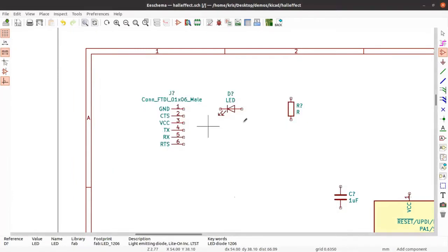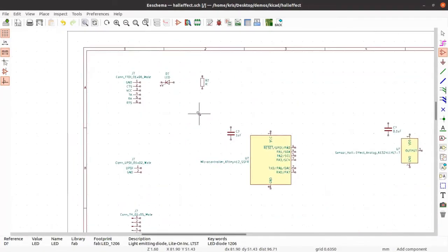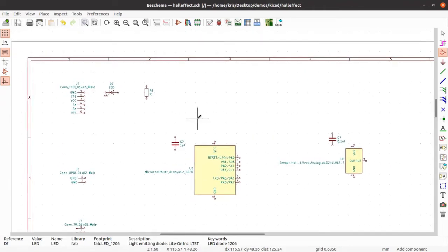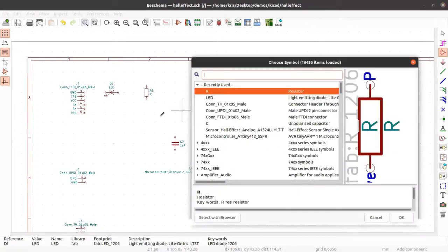Yeah. And so for some of you, it's going to be probably needed. If you really need to double check what is the voltage or the power rating for the sensor. Some of the sensors are powered with 3.3 volts. And for that, you will need to convert the incoming 5 volts to 3.3.